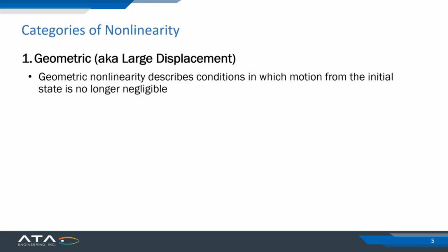That would account for situations where, for example, as the drum head is deforming, it is stiffening and able to take the vertical load through tension of the membrane. A clothesline is another classic example of that. It also could be the situation where you need your loads to update directionality as your structure deforms and moves through space.